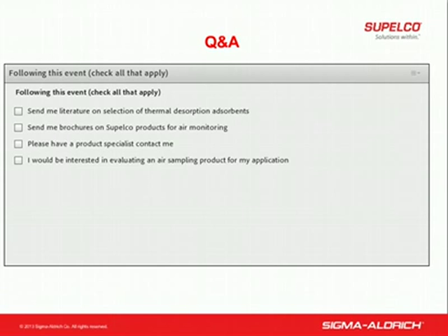What about the life of adsorbents, the cycle of adsorption and desorption? We're kind of saying that the lifetime of a tube is 100 cycles plus or minus 50, which is not always what the customer wants to hear, but that depends how gently the tubes are being handled. If the tubes are being shipped all over the world, we may only get 50 cycles. But if the tubes are localized to the place where the analysis and the sampling is taking place, it's easy to get more than 100 cycles out of a tube.